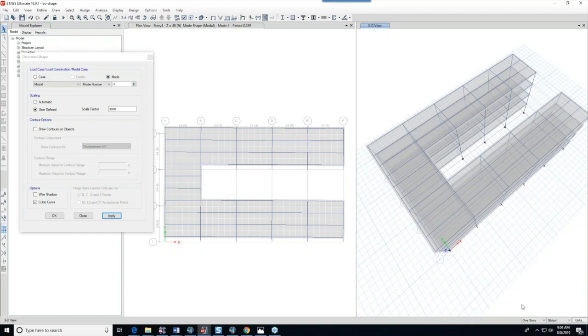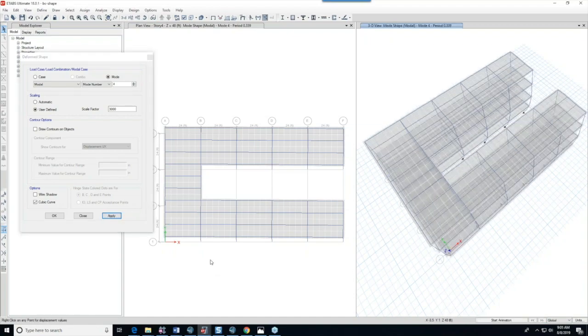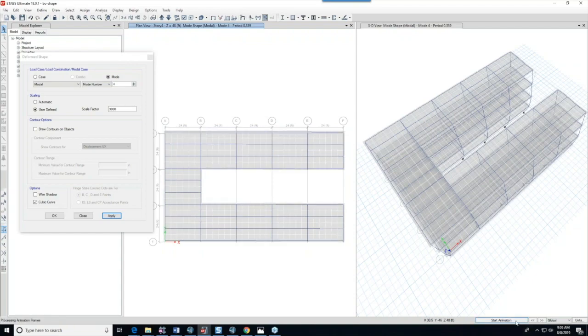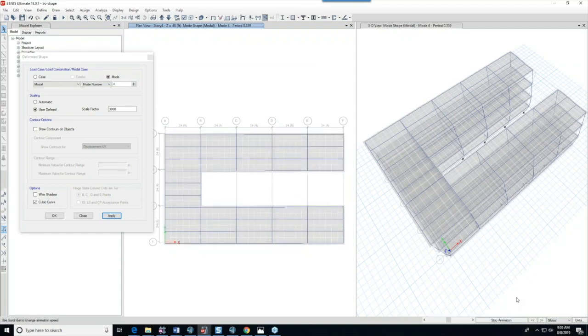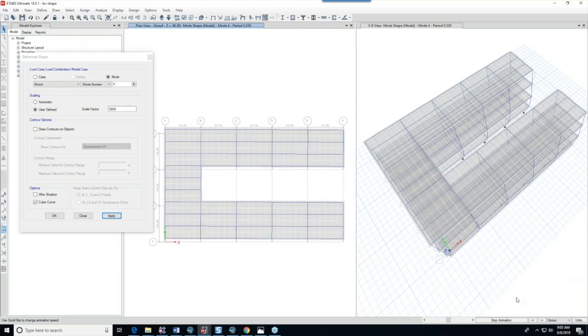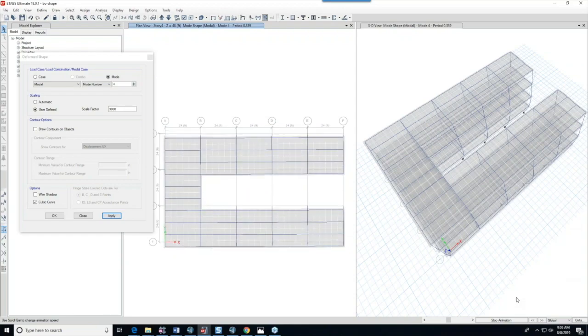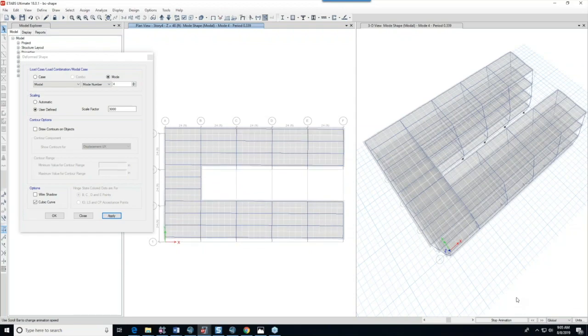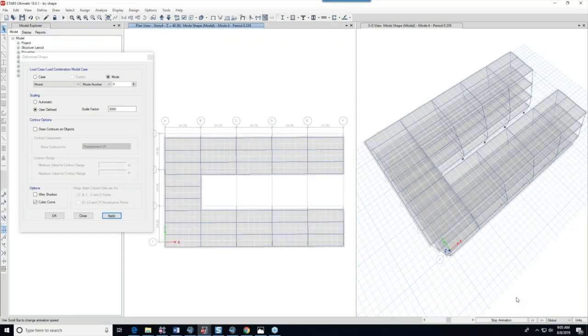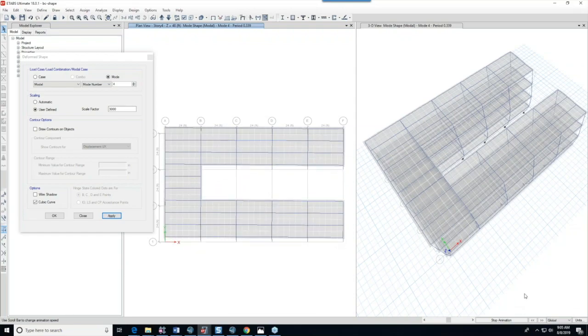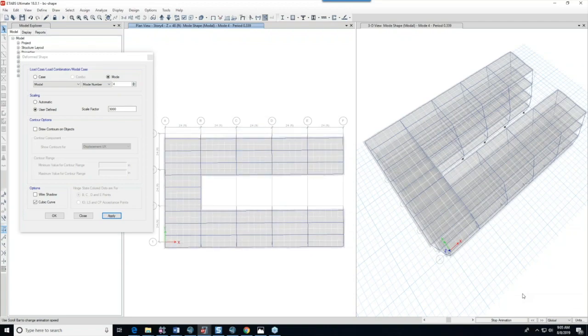And if I were to just look at a particular mode shape and look at the deformation of this floor and animate, maybe I'll look in this floor plan and animate the displacement, what you see is that the floor is behaving as though it's a rigid body. There's not a lot of differential displacement in the XY direction between any pairs of joints.